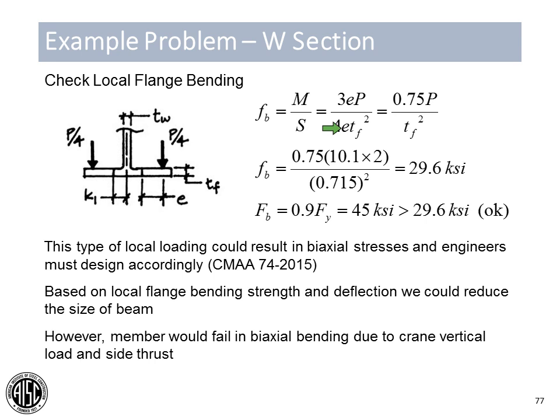Right. With those clamping systems, like if you use a Lindapter clamp, for example, like I had in some of the photos, you can get the diagrams of those clamps to see exactly where your clamp is going to be loading your flange. But as long as it's concentric loading about the center line of your member, it really will not matter. The farther out you are on the flange, the longer the effective length is right in here that will become engaged in the resistance to that flexure. Your S value here will increase.